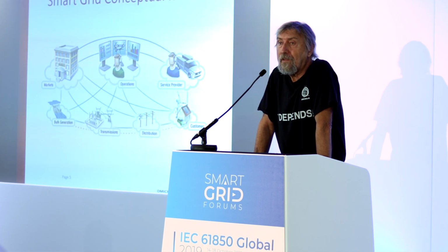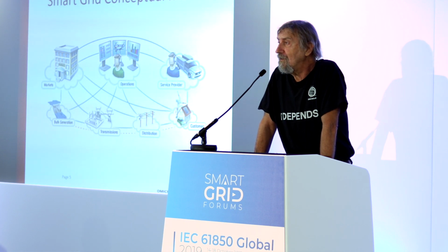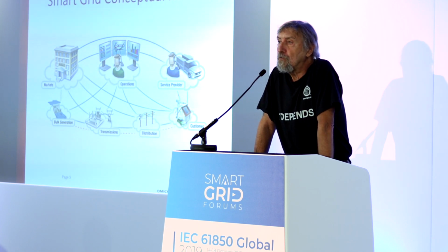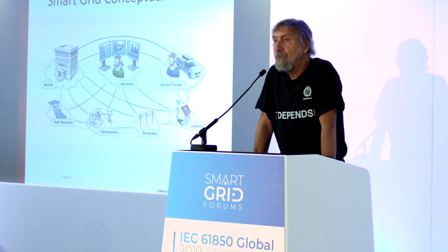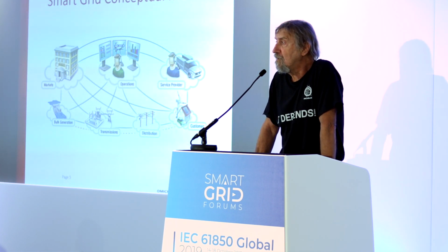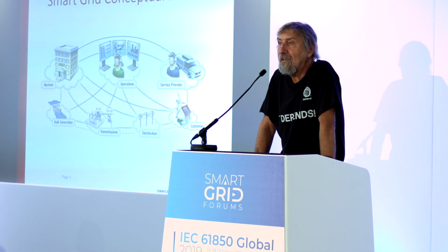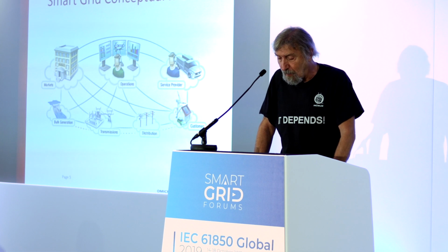So actually these people become what we call a prosumer today, because at a certain time when the sun is shining, they may be producing much more power than they need, and they are exporting this power, they're delivering it to the grid in order to support the balance between the load and the generation. So this is something that now completely changes the requirements for the protection and control of the distribution grid, because we may be having power flows in the reverse direction, or we may be having an energized line after the line is stripped from the substation. So this is a significant change as well.